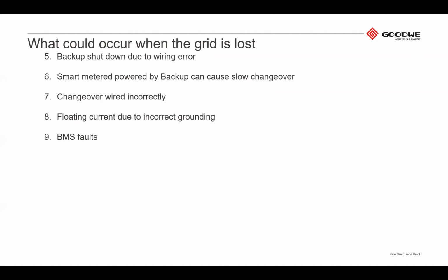So it's very important to make sure that those devices communicate correctly and that the batteries are installed as per the battery manual. So you must not miss any ground cables or anything like that. If the battery requires it, we need to make sure that everything is well equally potentially bonded on our grounding.